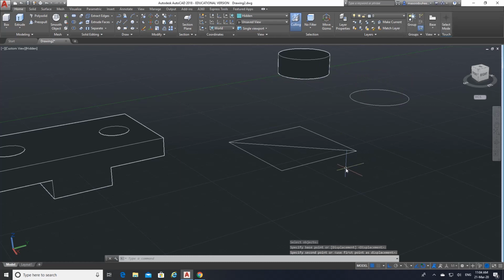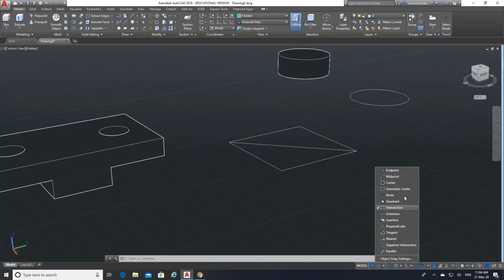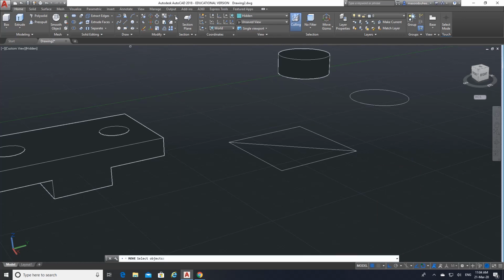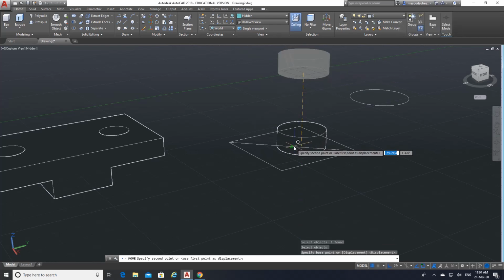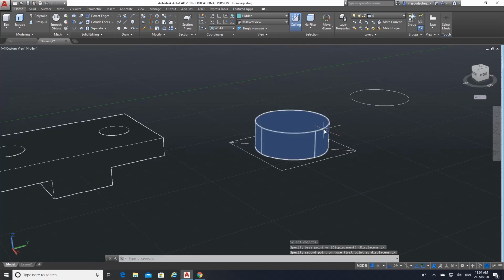So what I will do now is, before I go, let me bring this one and keep it over here at the midpoint. Okay, so here I will just go and select midpoint. I will remove intersection. I will keep midpoint and center. Okay, so now move this circle and click here. Enter. From where? See, don't catch this one, this center. Click, come down here. So where? See here, you see the midpoint here. See a small triangle in there. Click there. So it has already moved.